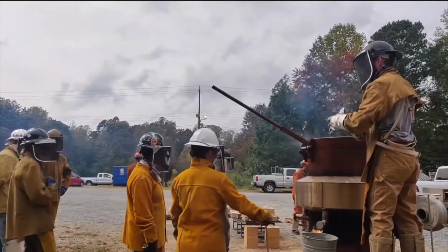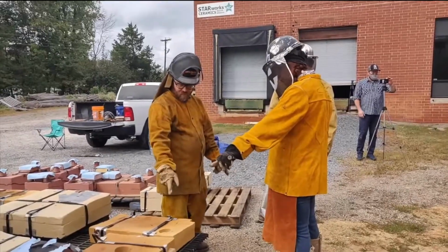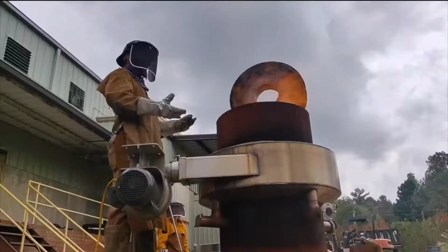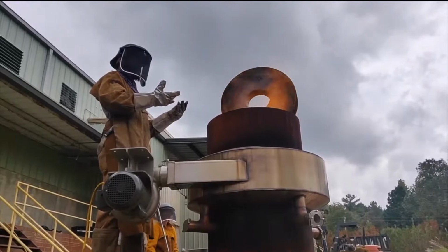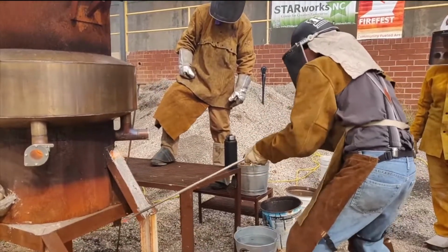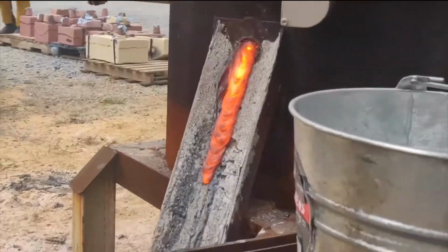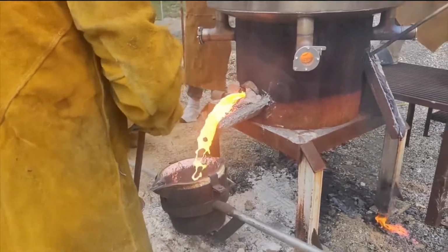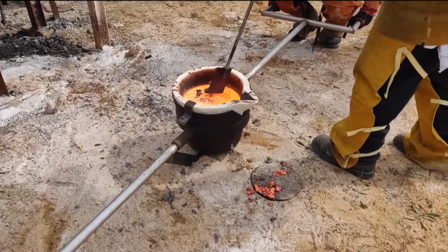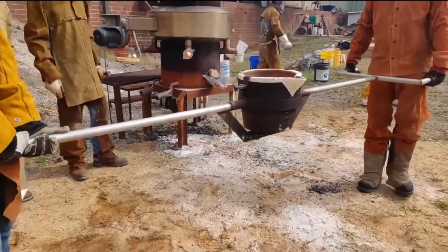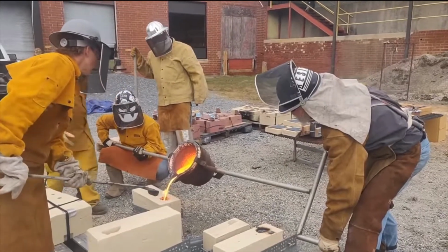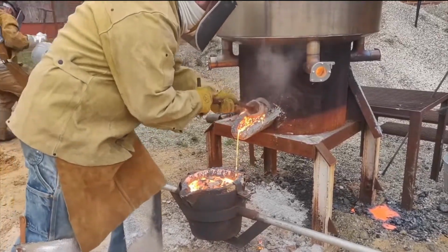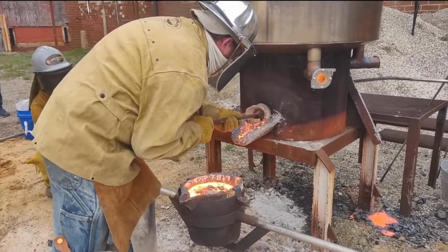There are specific assigned roles in an iron pour. Usually you have the pour master, who is the one who manages the pour team and directs the order of molds to pour into. The charger, who loads the furnace with coke and iron. The slagger, this person stands in the back of the furnace and keeps the flow of slag coming out of the furnace. The tapper, who breaks the seal open. The skimmer, who cleans the iron before pouring. Then the donkey and the pourer. The donkey holds the ladle steady while the pourer tips it over.